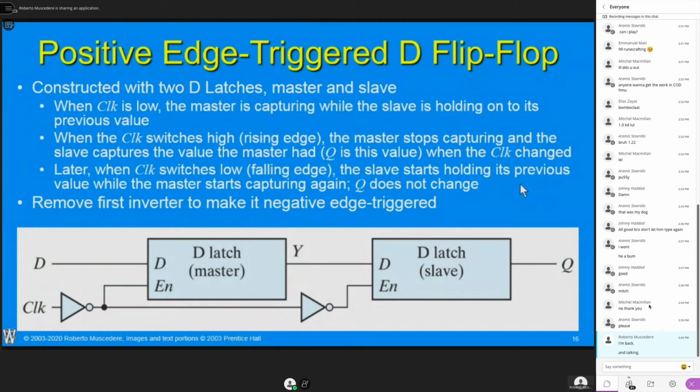Again, if I go back to the early 80s, we didn't use D flip-flops to build microprocessors and circuits. We used other little tricks. And those tricks worked as long as the device was in spec. For example, you couldn't take a CPU from that era and just clock it to a very low frequency to save power. It wouldn't work. It would fail because it was designed to operate within a certain clock speed. If you went over it, obviously the circuit would fail because it wouldn't perform its calculations correctly.